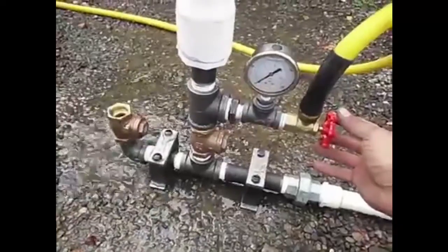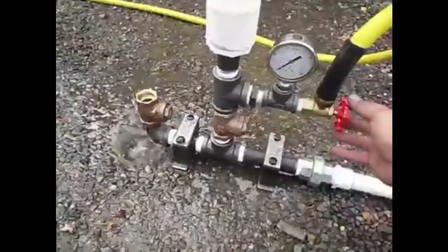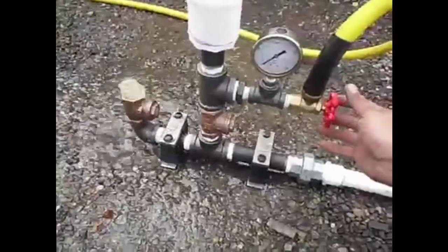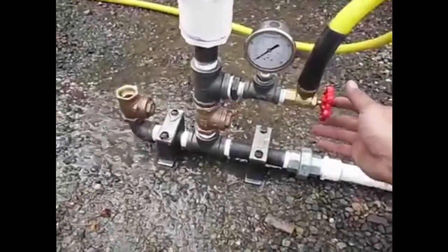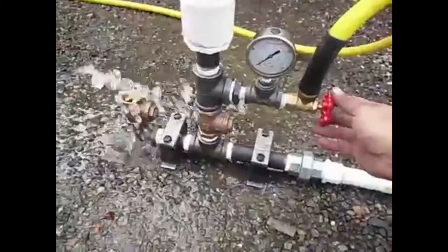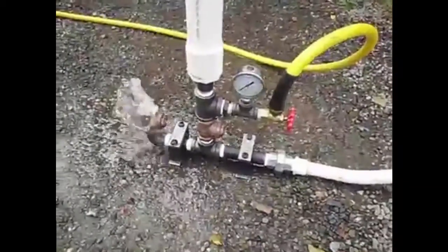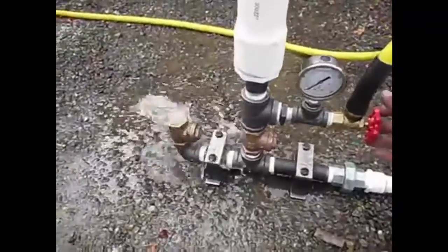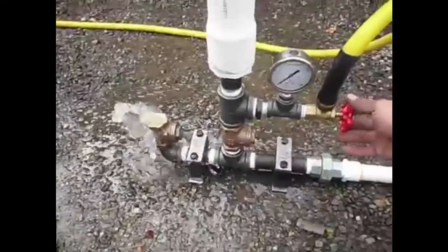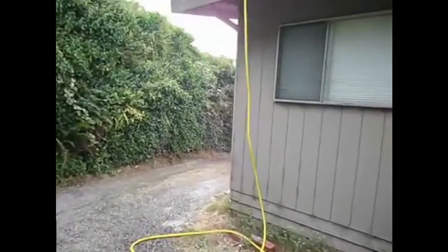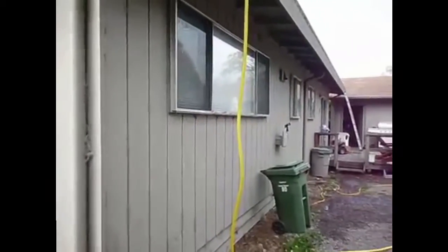Alright, here's a backyard example of a ram pump, as they call it, or a water hammer pump. Basically, he's got water rushing in from the right side of that PVC, and it rushes across the bottom into that waste valve right there. And once it reaches a certain flow rate, the valve closes. It smashes shut. The water will have a hammering effect. It'll go up into the arrestor and be pushed into the yellow hose, and the hose will take it to wherever it needs to go. In this case, on top of this guy's roof. I think he's just showing this as a demonstration.